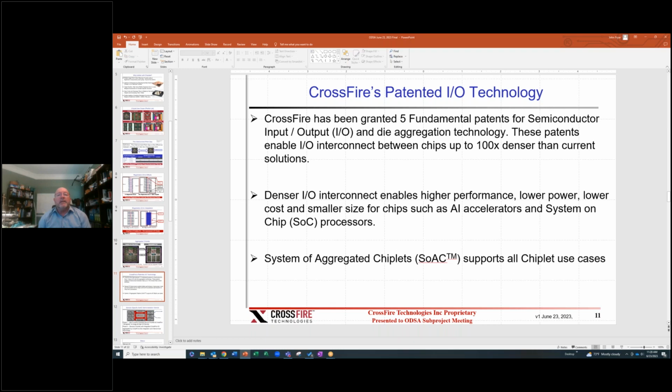But fundamentally, the answer is yes. We can apply RDL on top of the interconnect and bump it, and you can use it on an interposer. You can assemble it onto a substrate, depending upon the complexity of the device, how many signals in and out of the actual package part that you need.